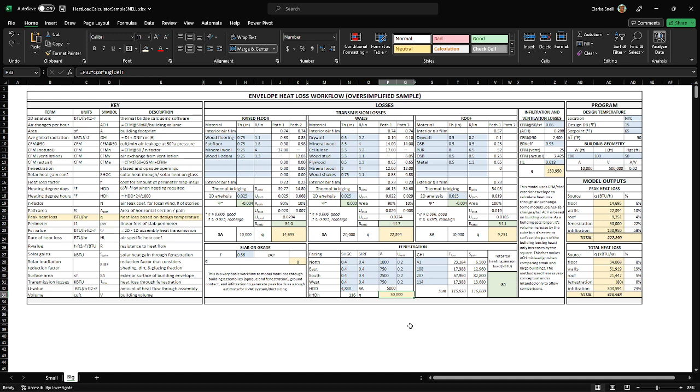Okay. Now we also have heat loss through infiltration. Briefly going over this, think about it: the surface area of your building is where heat is going to move through. It's going to be lost. So we have cubic feet per minute at 50. That's 50 pascals, so we need to define a pressure that this is happening at. So we're saying that we have a building sitting there.